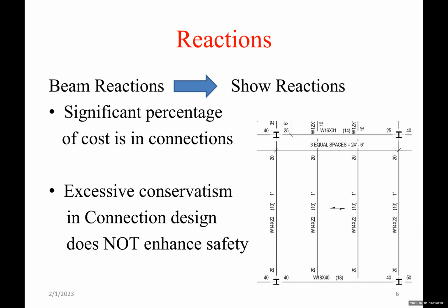We can get the capacity for that beam from tables in Part 3 of the AISC manual, and see what the capacity is in terms of reactions. We'll find that this is more than 100 kips. So why do I need to design for 100 kips or more if the reaction is only 20 kips?